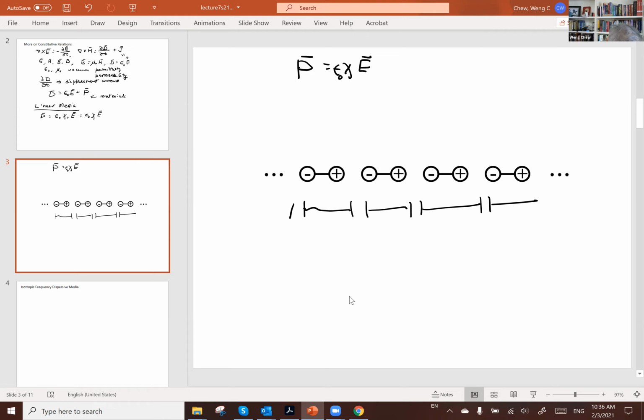And then maybe another piece of wire. So you can think of when these little dipoles are formed, small capacitors are filling all of space. And as we know, if we have a time varying current, if d dt is not equal to 0, then electric current I, a phasor I, can flow through a series capacitance. By the same token, if we have many of these dipoles lined up in space, they can give rise to displacement current flow, which is very much like electric current flowing through a series of capacitance. But we can also think of this relationship as a linear relationship where this is input and this is output.